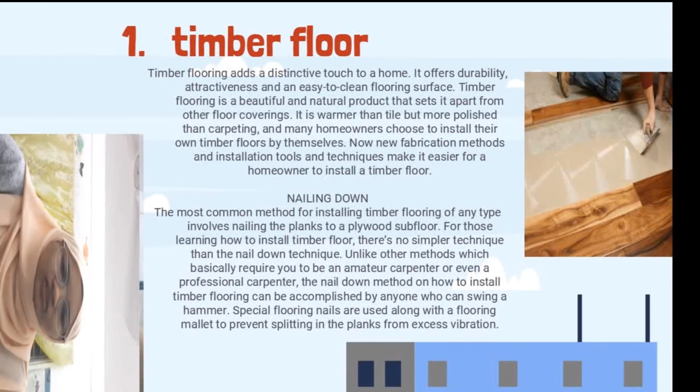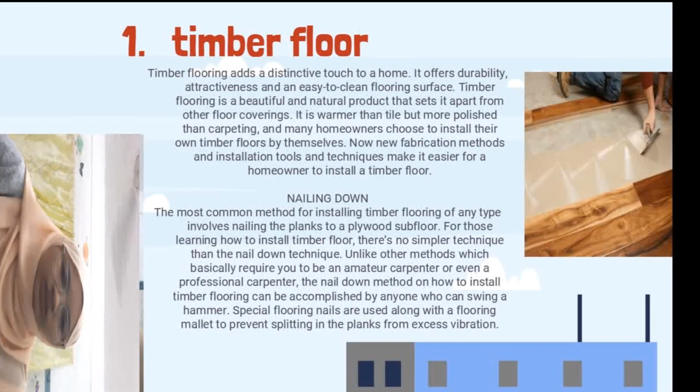Unlike other methods which basically require you to be an amateur carpenter or even a professional carpenter, the nail down method on how to install timber flooring can be accomplished by anyone who can swing a hammer. Special flooring nails are used along with a flooring mallet to prevent splitting in the planks from excess vibration.